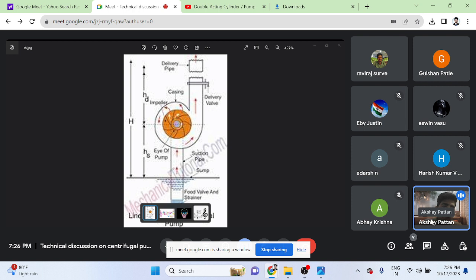Okay. So there is actually a small hole or pin inside the shaft which is sending a small amount of water into this gland packing to reduce the heat in the gland packing and to prevent damage due to the thermal stresses inside the centrifugal pump, right?